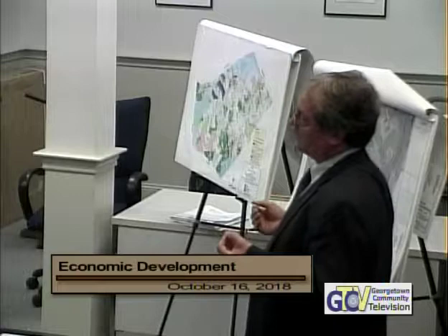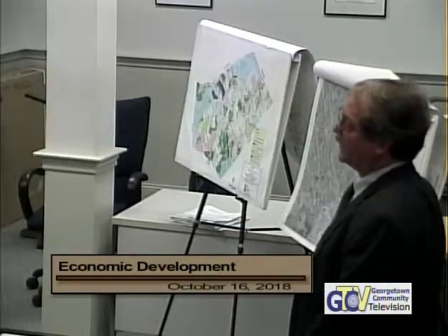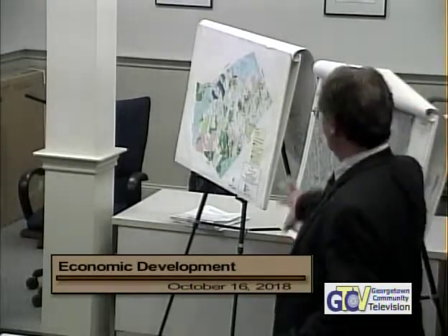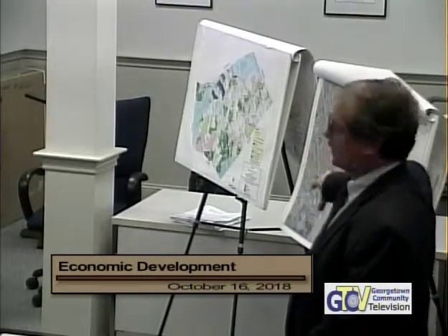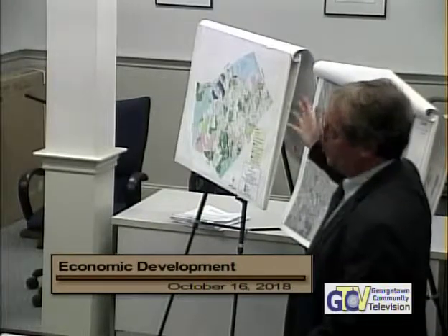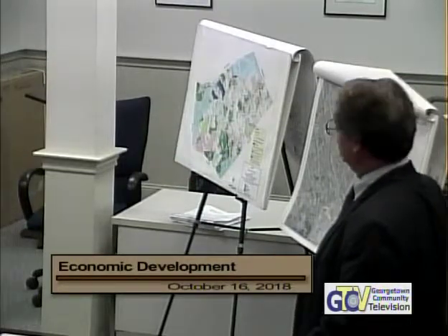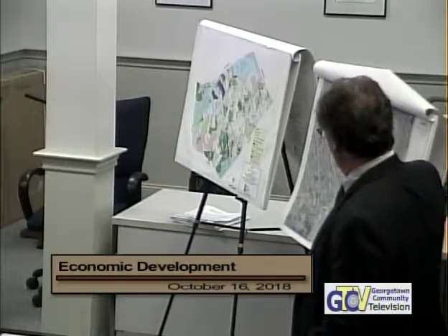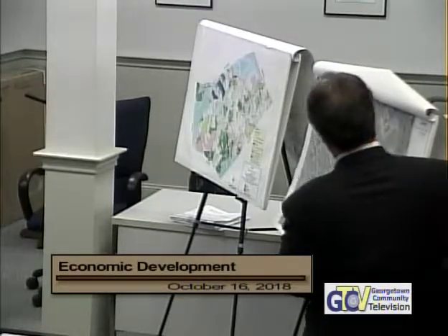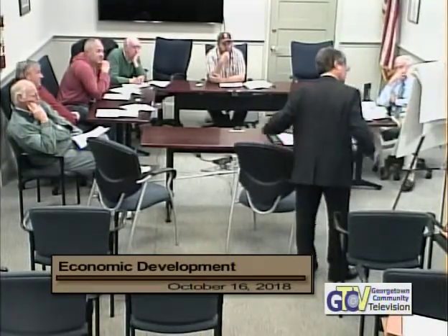Costs are high. Even though everyone likes gravity, you don't have to worry about it, there are no pumps, there's nothing else, there's a lot of expense to putting in gravity, especially in the town center. We would also have a pumping station down here to then convey it, and then another pipeline that would pump the flow to your final destination. I don't think you can dig a hole 8 feet deep in the center of Georgetown and not hit water. Right, you have to deal with water too. I think it's frozen someplace, and I'll find it at about 4 feet.